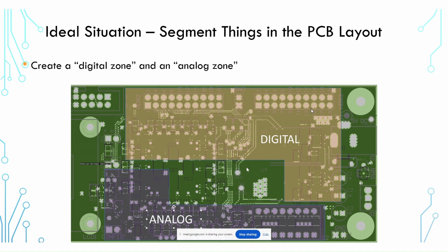All your other digital stuff you'd want to place up in this region so that it can talk to each other. And then same thing with your analog stuff. Your analog front end, you would want to try and create this flow coming away from no man's land and then existing only in these regions in order to confine that analog signal in one region of the board.